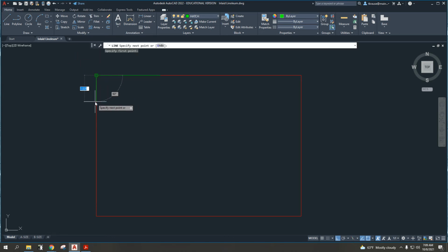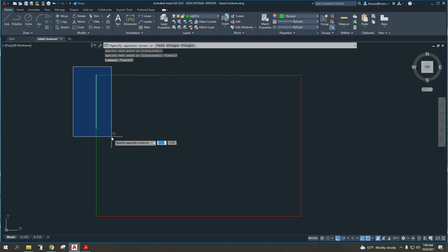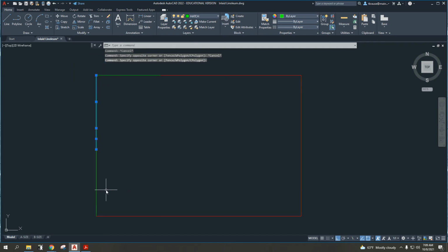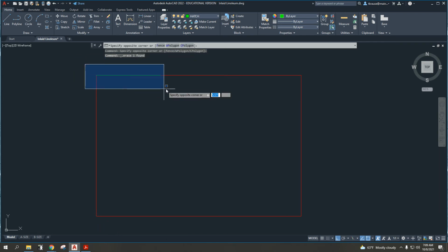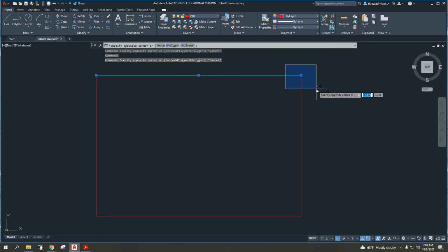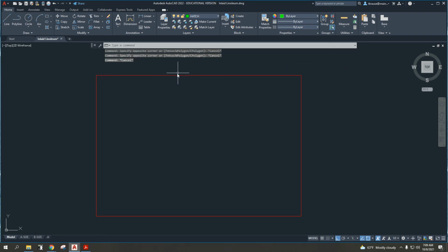Another thing that's somewhat common is sometimes people will draw a line, let's say this long, and then they'll draw another line that's that long. And then eventually they'll get over to here, and now they have, you see how it highlighted one line, two lines, three lines. If you've got something that is one line, a line is the shortest distance between 2 points. The 2 points, if I select this line, is the start of the line over here in the top left corner, and over here is the end of my line. I should not have multiple things going on for that line. Okay, so those are some bad habits.